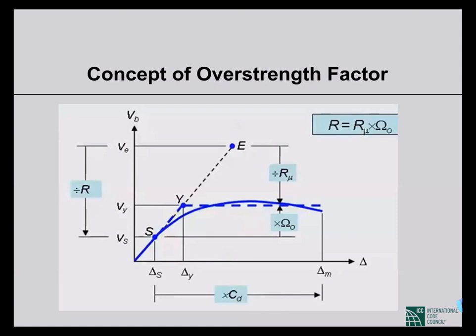But we have to understand one thing. This is not only reserved strength. This is the actual case. So in reality, although we design our structure for base shear Vs, and we become conservative to think that the capacity is S up to Vs, that is the capacity, and at the same time we assume a deformation like delta M, but actually what happens during the earthquake, the load actually comes. The load comes up to Vy.